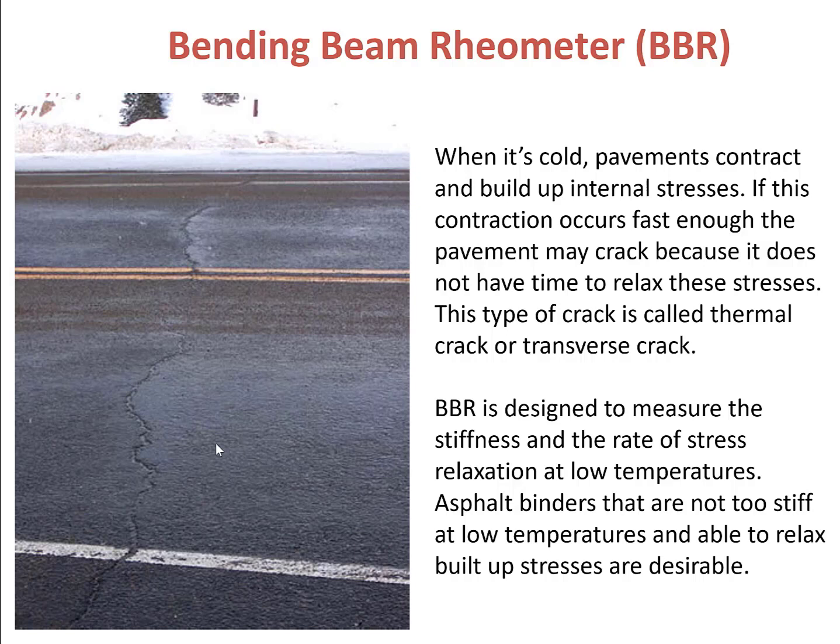A single severe drop in temperature can cause stress to quickly build up to a critical point to cause cracking, and this is called a single event low temperature cracking. And this particular temperature associated with these critical stresses is called a critical temperature.